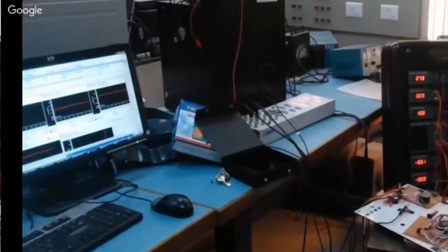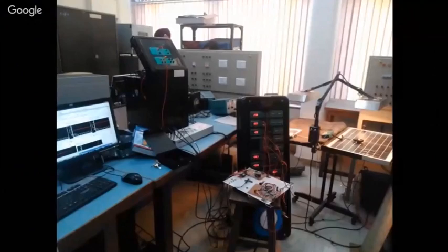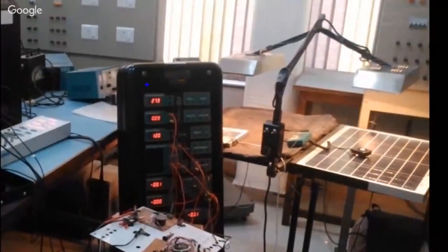So in this experimentation, you can see here, this is the dSPACE and there are 4 wires going: 1, 2, 3 and 4 wires are there. These 4 wires are nothing but the 4 parameters we took inside: temperature, irradiation, voltage and current, when we did the experimentation. So for irradiation, we made our irradiation meter here. You can see here, we kept a small panel here. For experimentation, we were using this panel. We just covered the other panel fully. There are 2 panels, we can connect them in series, but we took only 1 panel at a time.